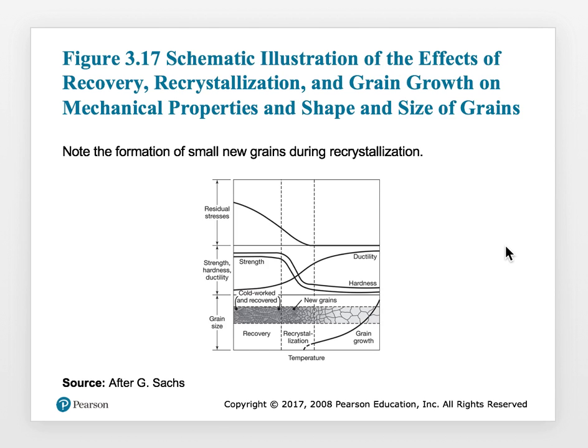So that's the process by which we make really large components, really thin shapes. So if you make a thin shape, you do not leave it in that shape. Okay, you heat it up such that you recover some of that ductility back. You remove some of the residual stresses. Why? Because if you have residual stresses, those residual stresses can actually work against you in the actual service itself.